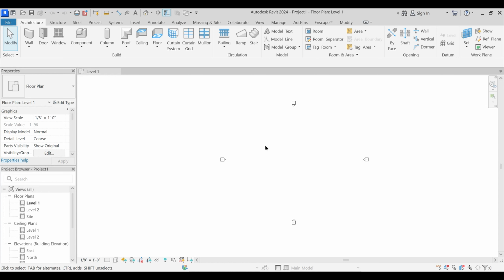Fine. So now the first step that comes into the picture after loading up this blank screen of Revit and coming to this particular project environment is setting up levels. Fine. So these are the elevation markers. See, wherever I hover my mouse over this, you read that it views elevation north.